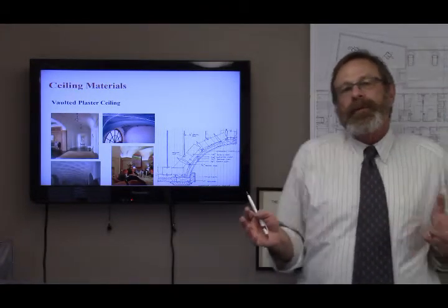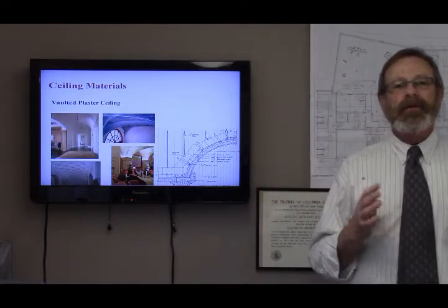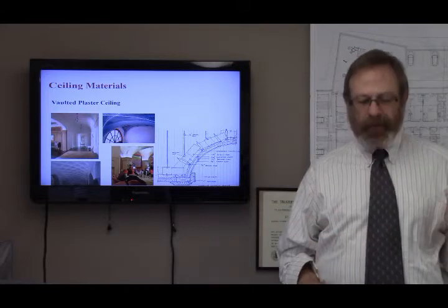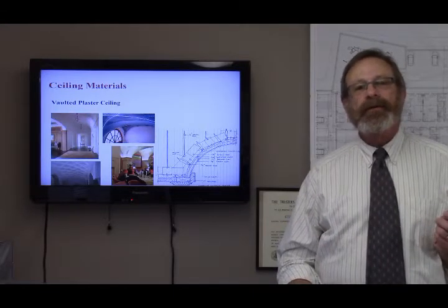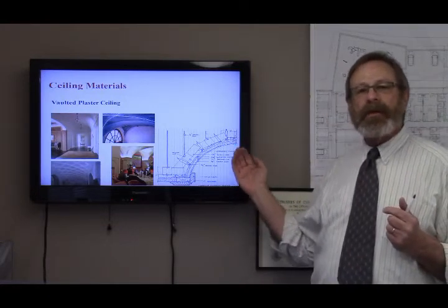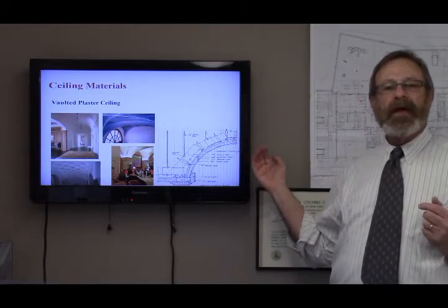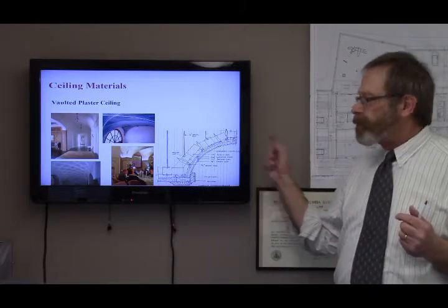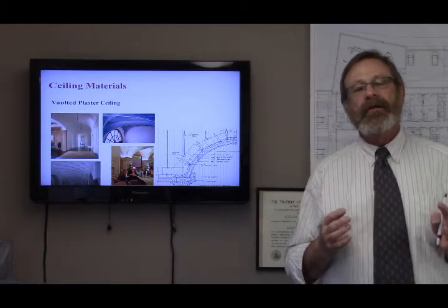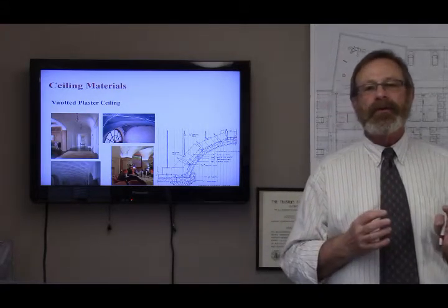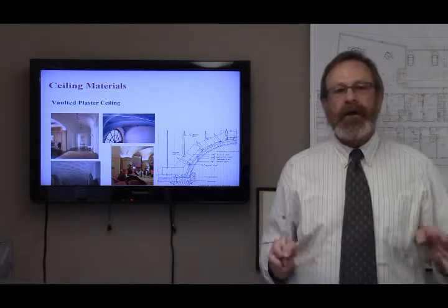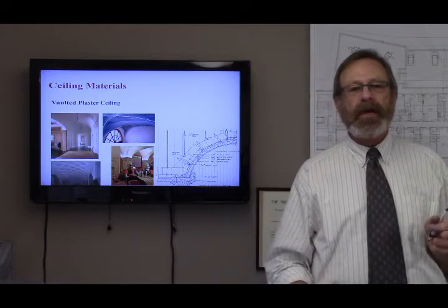So the tradesman cuts a piece of plywood templated to match the curvature of the arch, which you as the designer have determined. When they pull that templated piece of plywood parallel to the arch, while pressing the template against each of those grounds, smoothing the plaster surface as it travels, lowering high points and filling in low points with the excess plaster, the arch is created. The arch shape or form is created.